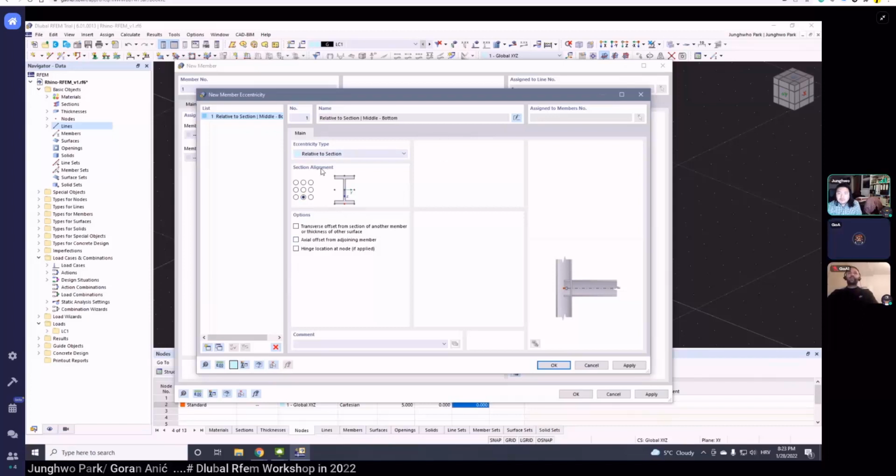I have a question. Why is eccentricity important for structural engineering? Most of the time you get the center position, the center of gravity, the axis of the beam from the model. Yes, most of the time it's the center of the beam, but sometimes it's important how this beam is positioned, because if elements have some eccentricity, then you have torsion moment, you know.